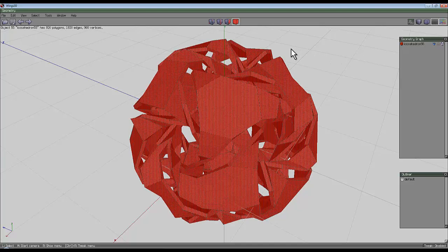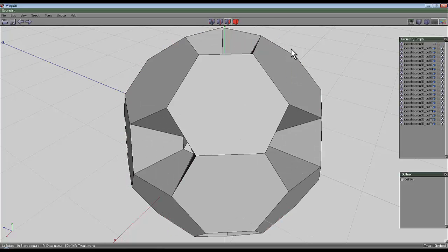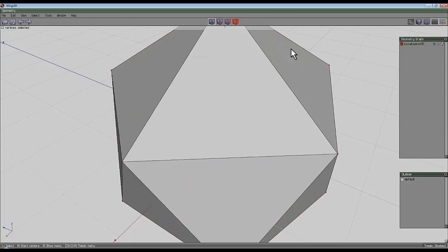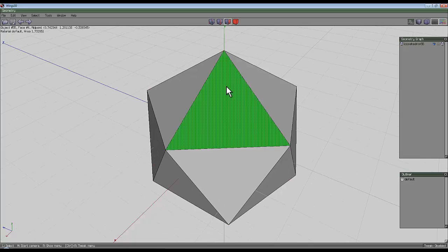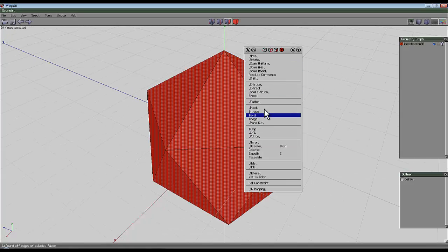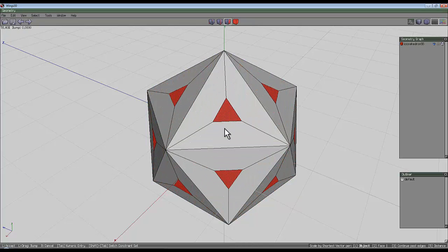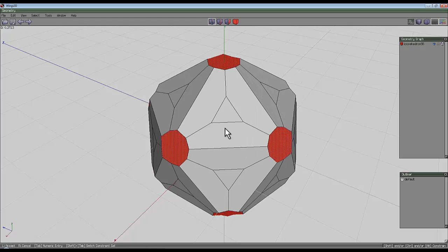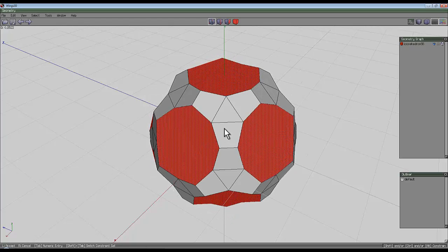So I'm just going to go back, right back, just go back to where I started. So there, and put the ports in. So select one of the faces and inset that face. Now the reason for doing it at this stage is because it generates extra edges, and that could change the overall geometry. So the ports have to go in first in this case if you want this to work. So select corner, identical, and then bevel that down. Now your limitation on beveling here is when these faces meet these inner triangles. So this obviously ended up a bit longer.